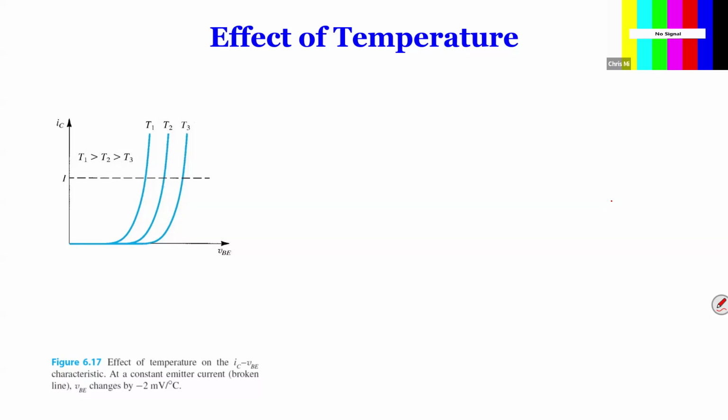One is the ambient temperature, the environment temperature. The other one is the device temperature, right? For example, if you're using your phone here, the room temperature may be, say, 22 degrees. But as you use it, the chip temperature goes up. Or when you charge your battery, it goes up. When it goes up, the whole thing actually changes. The direct representation is the junction voltage. For the same junction voltage, the corresponding current will change. So that impacts a lot of applications.